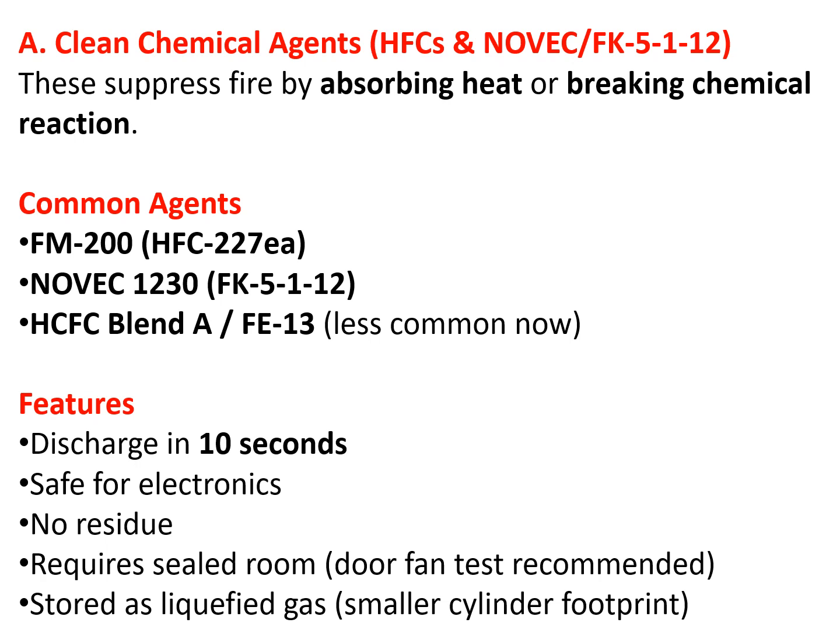Dear friends, we were discussing total flooding system, out of which the first one is employing clean chemical agents. These agents may be HFC or Novec. This suppresses fire by absorbing heat or breaking chemical reaction.